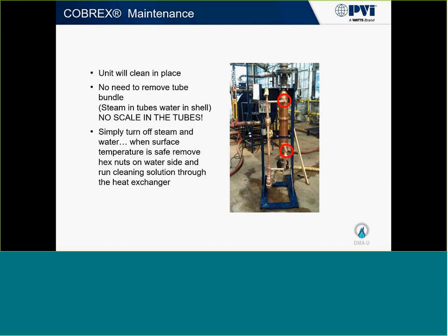From a facility maintenance point of view, it's nice because we can clean in place. That's one thing that a lot of universities and hospitals really don't like about maintaining a traditional steam water heater, because of the amount of man hours and how hard it is to maintain the heat exchanger in it. Traditionally they might allocate an entire day to break down their steam water heater, take out the bundle, clean it, descale it, do all that stuff. With clean in place, it's a lot easier to do that.